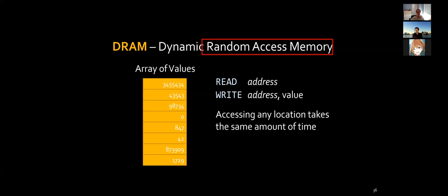Okay, so hopefully you understand that answer. Sam asked a very good question. Does this make DRAM more power hungry? Absolutely. DRAM is very power hungry. In fact, the memory subsystem, especially DRAM, takes as much as 30 to 40% of all the power and energy consumed by your computer.